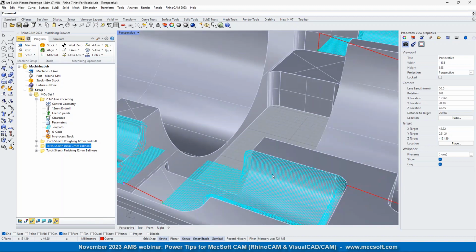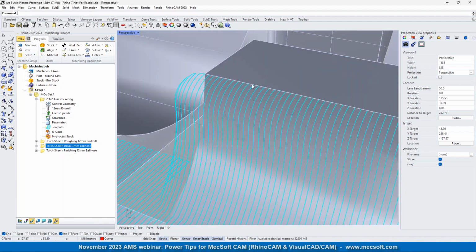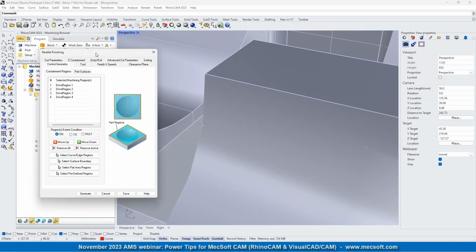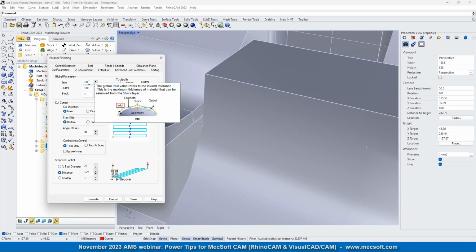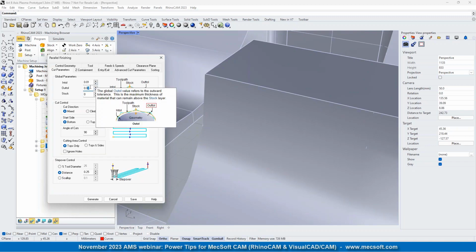So we see we have all linear motions. Okay, the light blue are all linear motions. And the number of segments in that motion is fully dependent on your tolerance. So if you go into here in your tolerance and you tighten up the tolerance, currently this is in millimeters, okay? Millimeters, we got 0.03 for in tolerance. If you change that to 0.1, say, which is a tighter tolerance, and you can do the calculation, convert that to inches if you want. That's probably a thousandth, maybe, or a little bit more. 0.1, and you generate that.